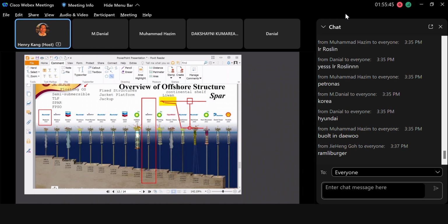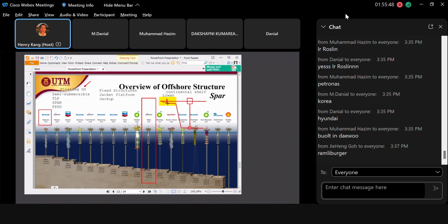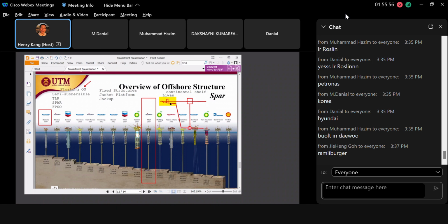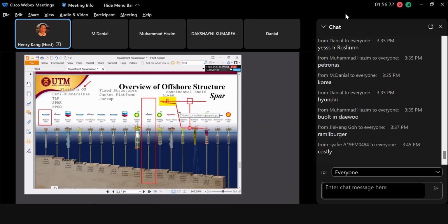However, the Chinese oil and gas operators' solution for the new one is very different. They try to build a jacket here in the shallow water region. Then they build the subsea pipeline connected from here to here to here. You get my point, right? So they build the structure far away horizontally from the oil reservoir, but they connect the jacket structure with a very long subsea pipeline, pumping the oil and gas more than 1 kilometer.